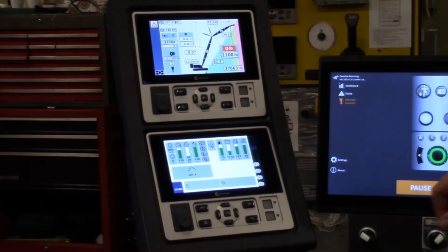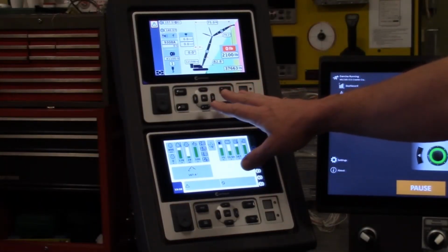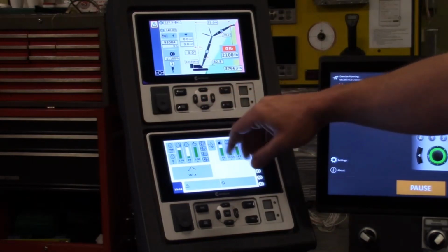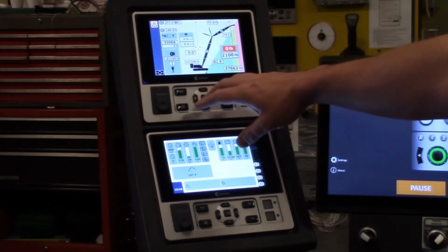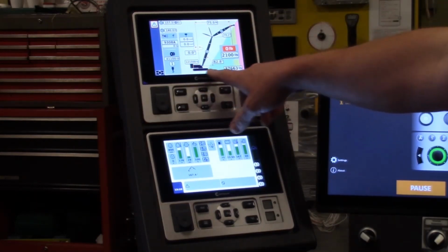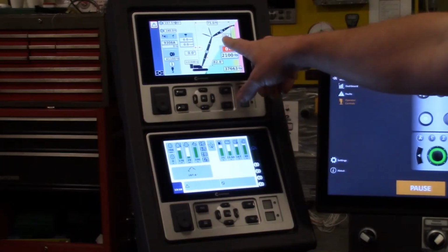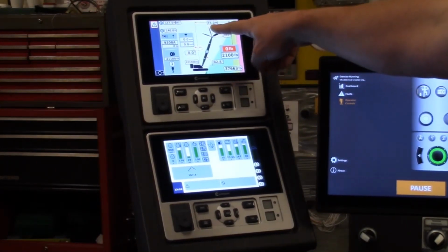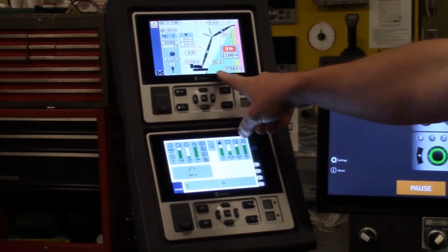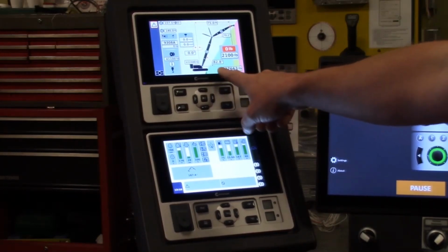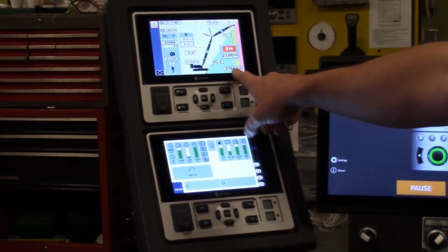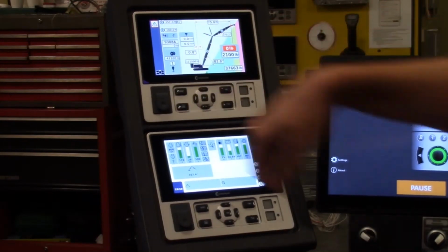So with the scenario loaded, we went ahead and set up our RCL. So here we have our RCL screen all set up. It shows our counterweight configuration, main boom angle, luffing jib angle, our radius here, and then we have our utilization across the bottom with our load utilization here. It also shows us boom lengths up here in the corner.